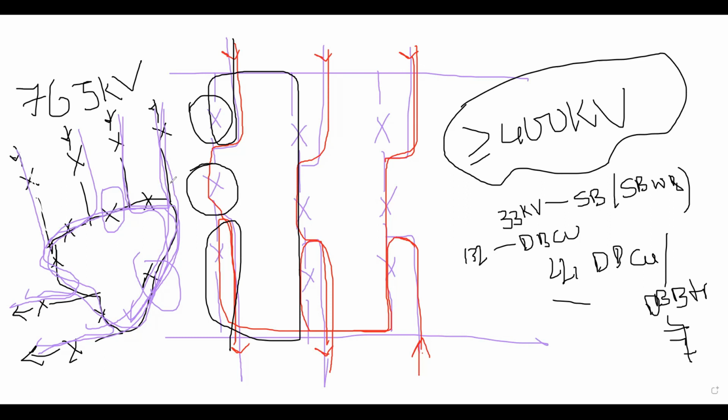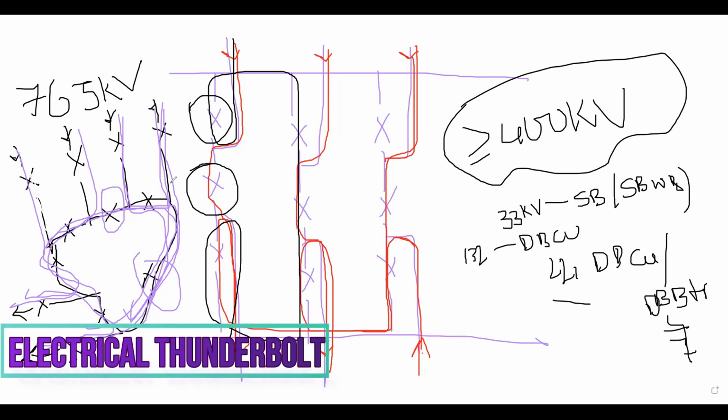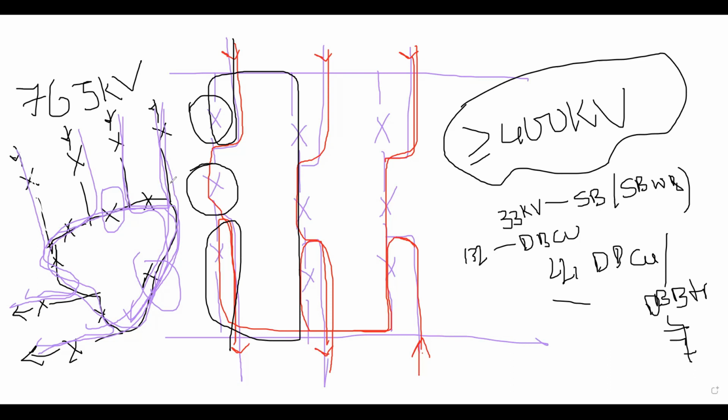As per the electrical utility guidelines, it recommends that for 33 kV systems, please adopt single bus bar with sectionalizer schemes. And for 220 kV, double bus with coupler or a more reliable scheme. And 400 kV, obviously a 1.5 breaker scheme. 765 kV, 1.5 breaker or ring main scheme. This is the practice in the utilities.